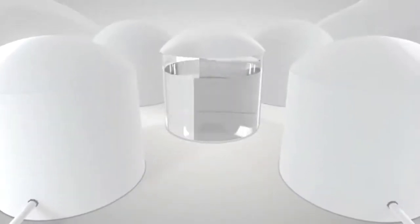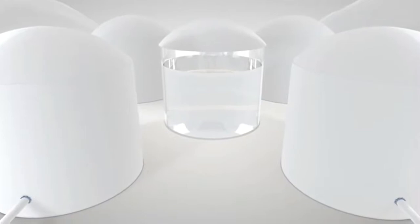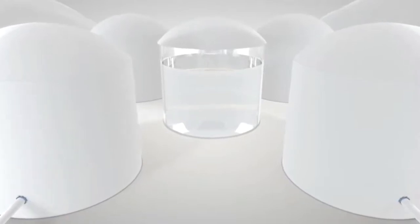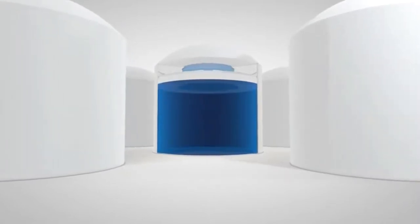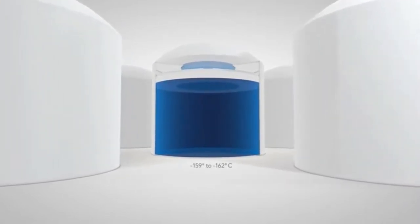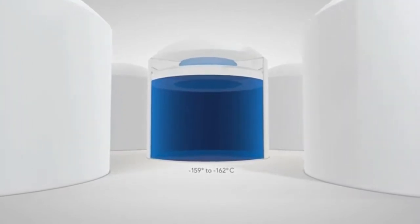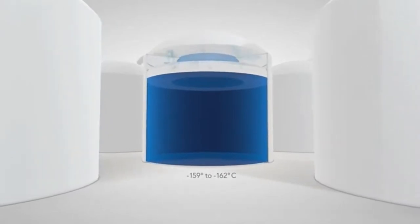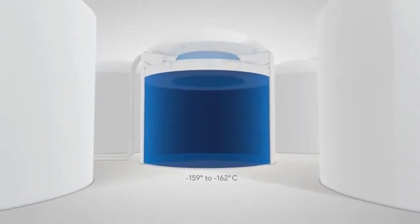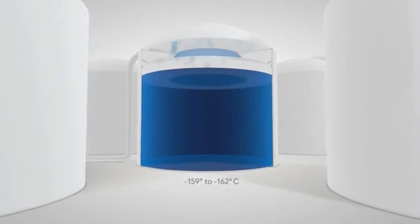Liquid natural gas looks like water except that it boils off at room temperature. It's odorless, colorless, non-toxic, and virtually non-flammable. The cryogenic LNG stays in these storage tanks at a constant temperature between minus 159 and 162 Celsius. Evaporation helps keep it cool and liquid while it's stored on land or in the ship. We capture the vapors and either burn them for fuel or we recondense them and send them back to storage.